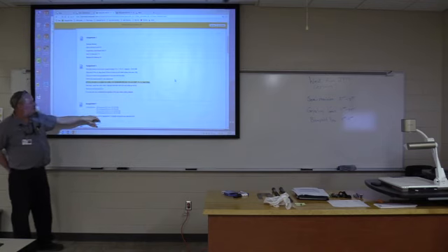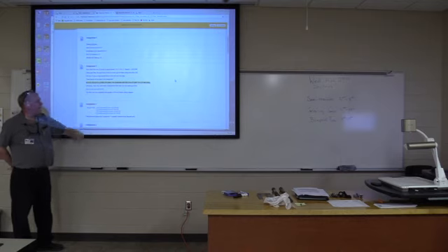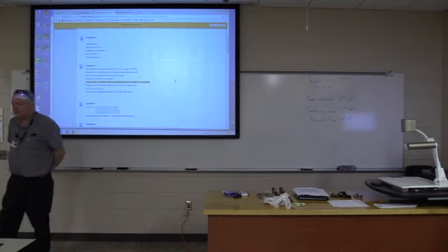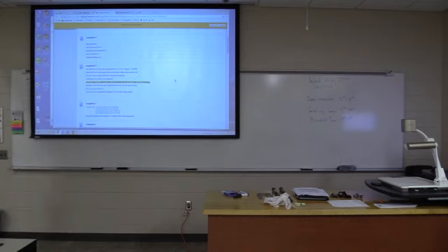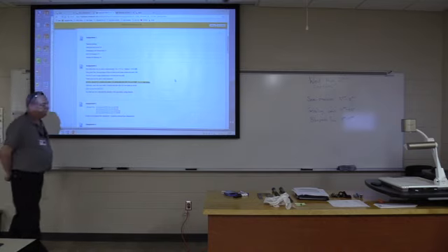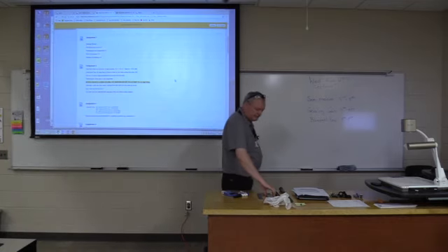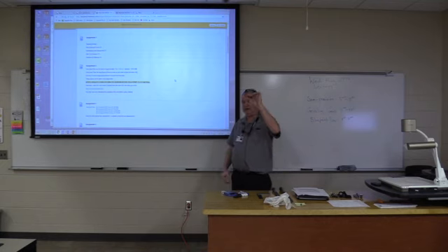And then this is the next assignment, something called Component 1001, something called Component 1002. So what you're doing is rough cutting, saw cutting your blocks for those assignments. Just one, rather, cut 2 blocks, and you're going to file up and clean up 2 blocks. Now, if you use the bandsaw correctly, what I have is material that is a 1/2 inch thick.